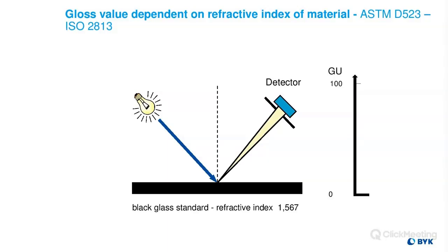So in general, the gloss unit scale goes from about 0 to 100. That's not the maximum end of the scale by far, but most materials, most paints, most plastics are going to read at about 100 or less. Sometimes you might see single digits or teens, but really it stays below a certain amount for most materials, and that's because there's a significant amount of absorption for paints and plastics. No matter how glossy the surface is, that surface is always going to absorb some of that light, and so it sort of limits the maximum gloss level.